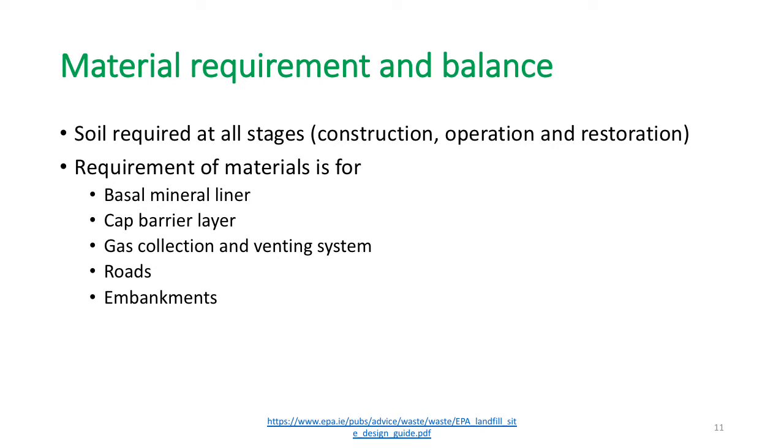So it is important that the designer should estimate the quantities of the material required. Requirement of materials is for basal mineral liner, cap barrier layer, gas collection and venting system, roads and embankments. So, to obtain the balance, the deficient material needs to be imported.